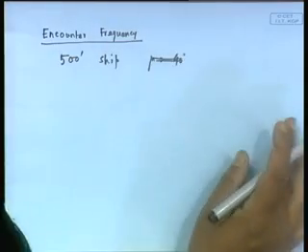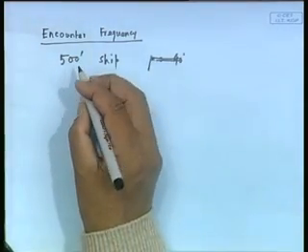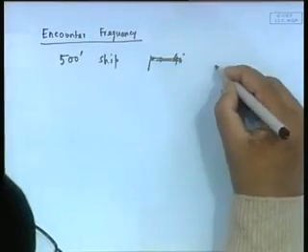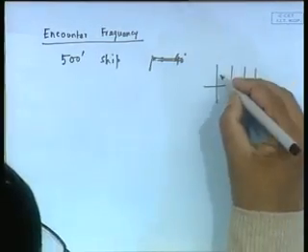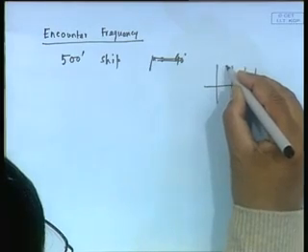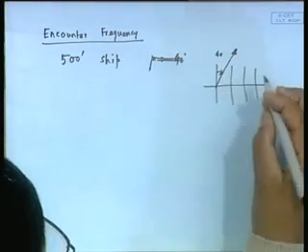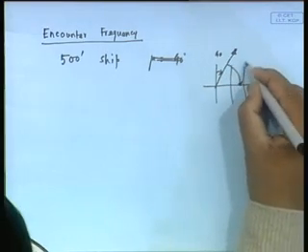Now here it does not say mu equal to 40 degree, actually I will tell you what it says. It says it is travelling with an angle 40 degree to the line of wave crest. So there are wave crests. It is travelling with an angle 40 degree to the line of wave crest. That means it is travelling with this as 40 degree. But remember, the waves are moving this side. So therefore the mu is actually 50 degree.